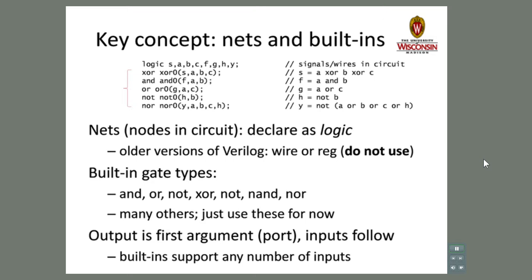In Verilog, we call these arguments ports. They look like parameters in a high-level language function call, but they are not that at all. In a program, a function is called at some point in time as the program executes. In structural Verilog, an instantiated gate is always present and constantly for all time evaluates its inputs to generate its output.